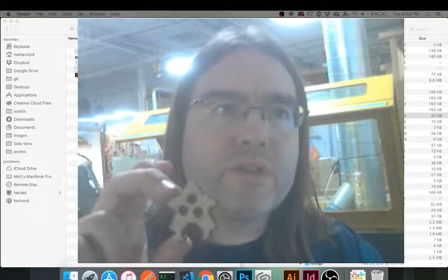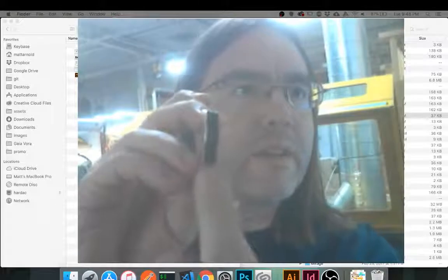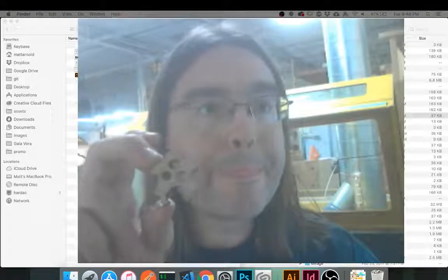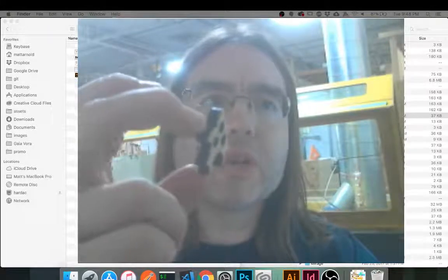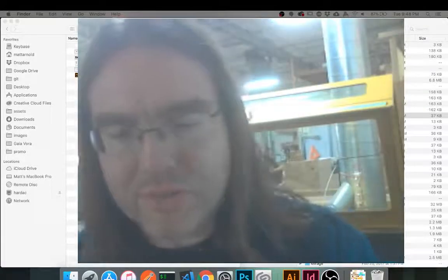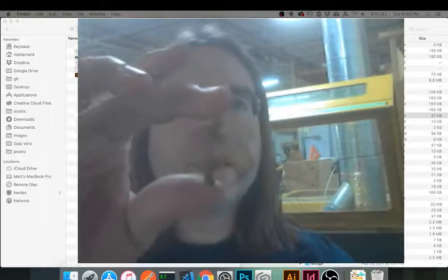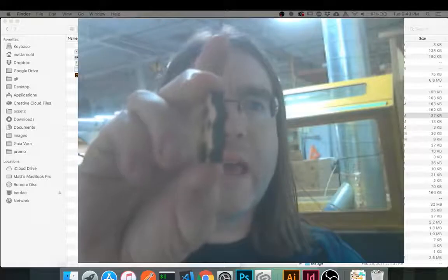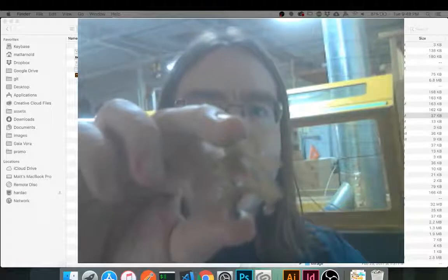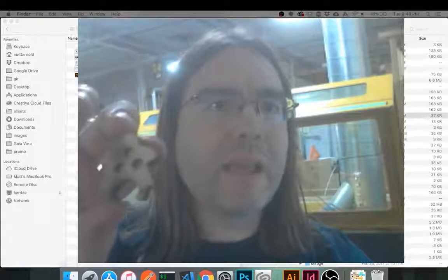What it'll do is turn into resin. The glue, as it burns, will create a resin coating along this dark edge here if you were using plywood. It's really tough to get paint to stick to it. So I use a piece of solid birch, or sometimes I'll use solid pine, or maple. Maple if I just want to use some expensive wood. That way it'll hold paint much better when I actually end up spray painting this. And the best paint to use, spray paint or with an airbrush, the best paint to use on a Meeple is actually model car paint, enamel.